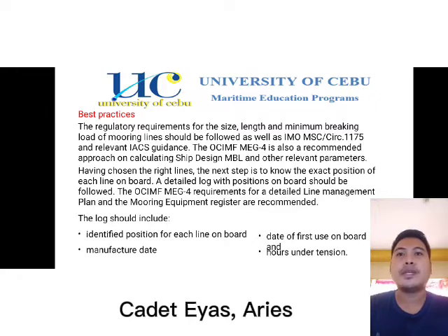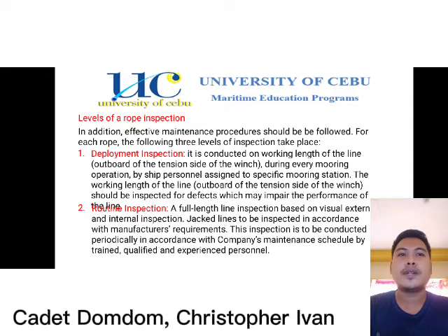The log should include, the first one, the identified position for each line on board. The next one is the manufacture date and the date of first use on board, and lastly the hours under tension. That's all. Thank you.